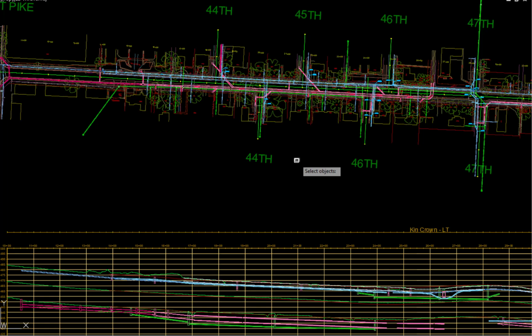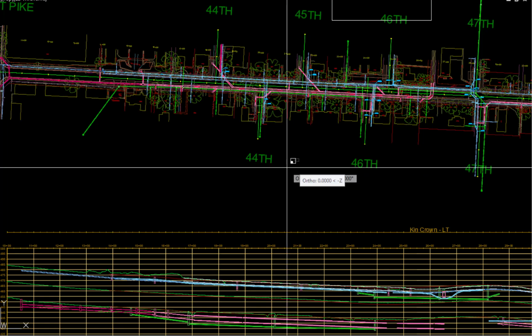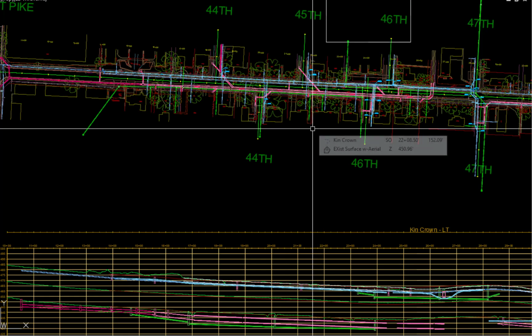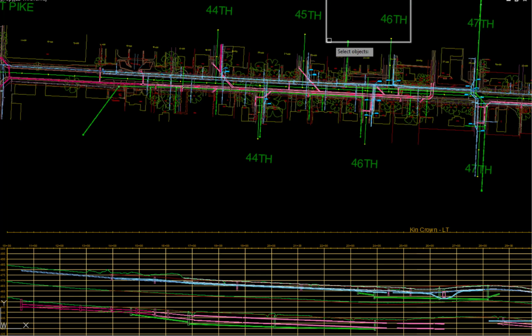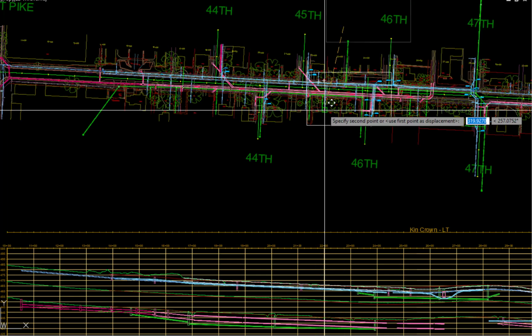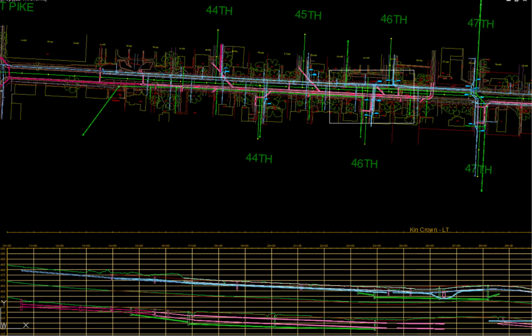SC, enter. Select the object, enter. Pick a point anywhere and select 20 for the drawing size. Move the rectangle to the desired area. M, enter. Pick the rectangle and move to the desired location. All check plots are made ortho to the current UCS, the user coordinate system.